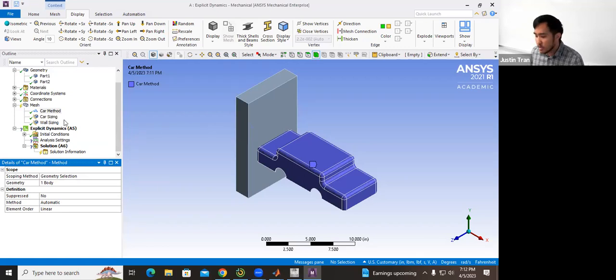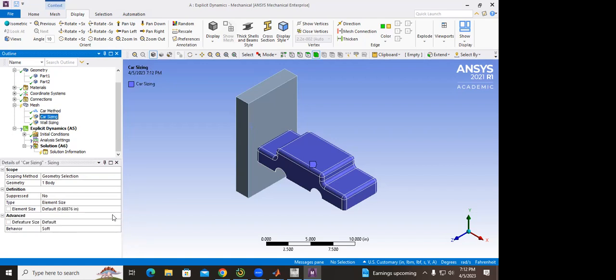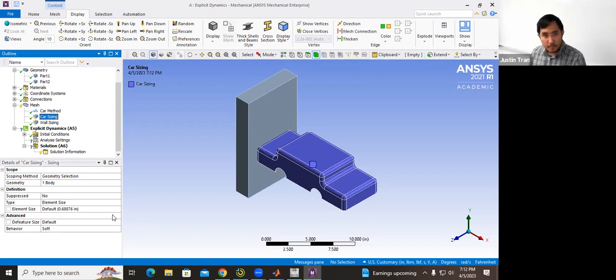We've talked at length about the issues with linear elements, and so you really want to make sure that you have a fine enough mesh for the car in order to capture all of the behavior. I have a question, sir. Yes, go ahead. Does using linear elements make our simulation less accurate? It does, yes. So you need to make up for that.